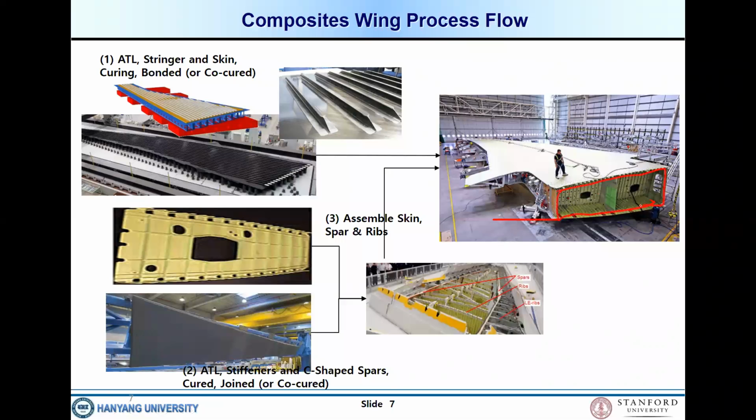We call it a box beam. This box beam is a part of this wing in the nose and edges. And so this part is a major structure which will support all the lifting force. This skin is just a skin which will control the airflow.